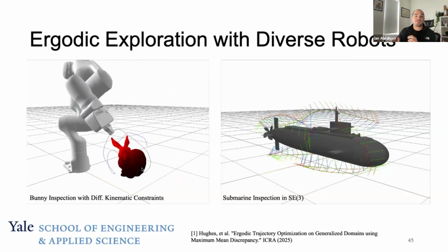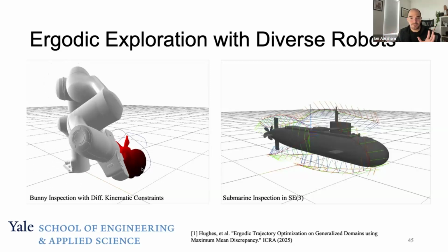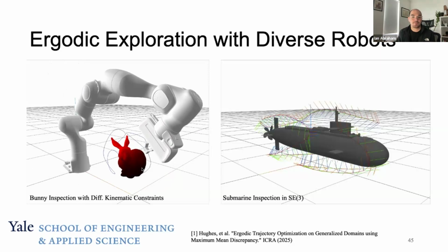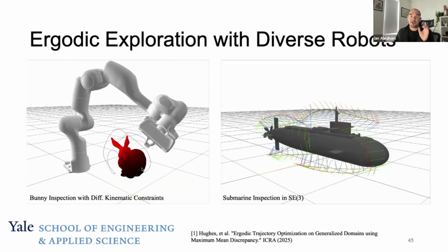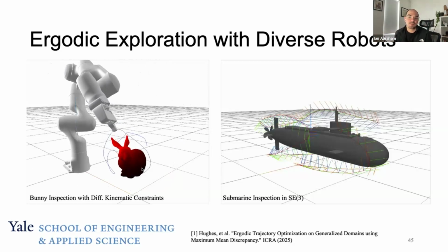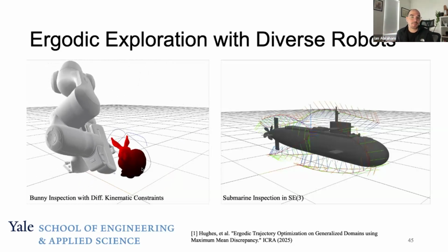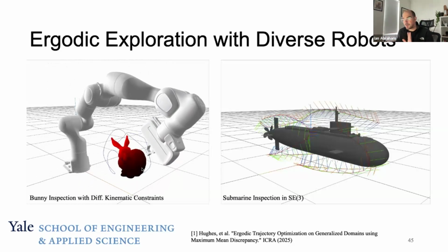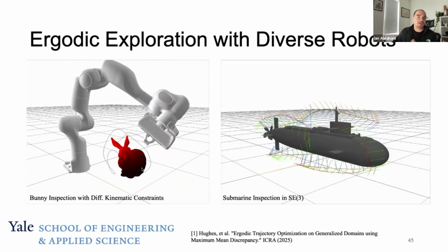The reason we wanted to avoid this is that I can't have this all the time. I want to generalize this as much as possible. The easiest way to generalize is to say I'm only taking samples, so anything I can sample from is okay. But I do lose those spectral behaviors, especially at higher frequency. I would have to eventually sample almost infinitely and resample to get that kind of behavior. For the most part, it looks very similar. It's the long-term behavior that we lose out on.